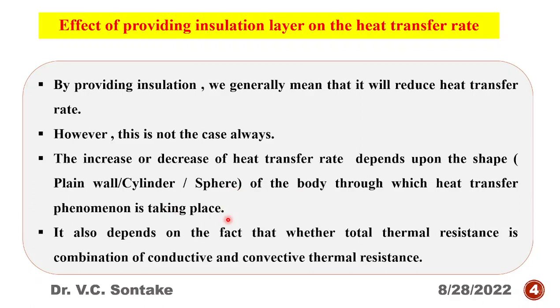The increase or decrease of heat transfer rate by providing insulation will also depend upon whether the total thermal resistance is a combination of only conductive thermal resistance or of conductive and convective thermal resistances.